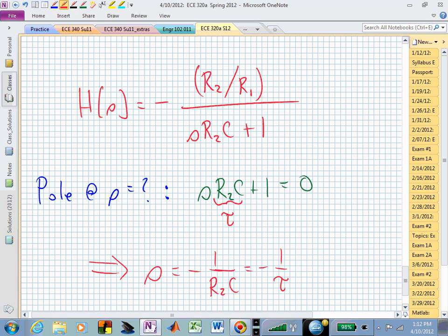So now the question is, we're getting ahead of ourselves from what I wanted to talk about today. What if you had 2 poles? Then what's going on? This is fun though, isn't it? So now we have 2 poles. What's going to happen? If you wanted to create a low-pass filter, you might put them right on top of each other and have them both cut off at the same frequency. You may say, let one be at 2 and the other one be at 2. And then I'm going to fall off more rapidly because I have 2 going instead of 1.